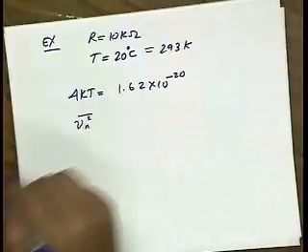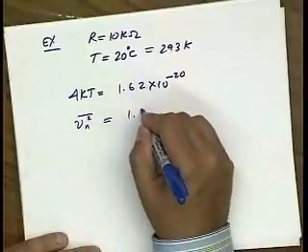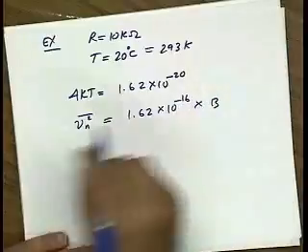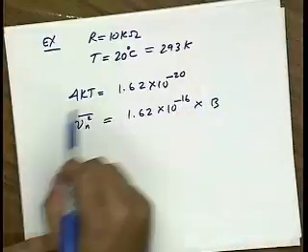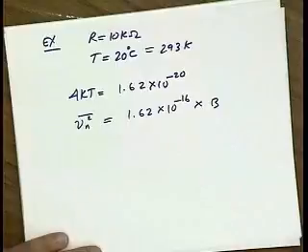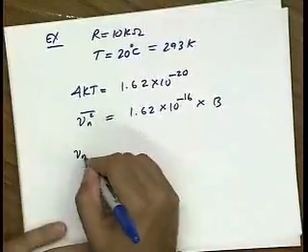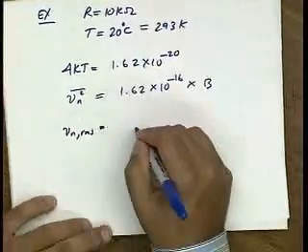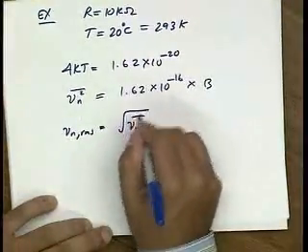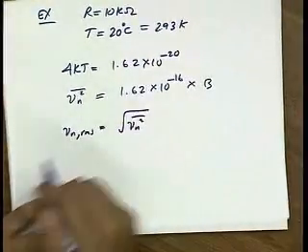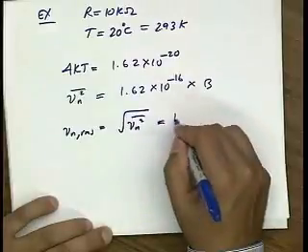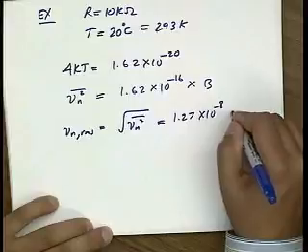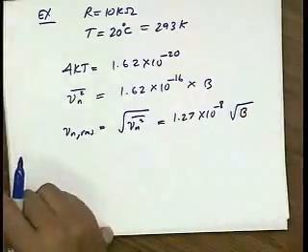So if I plug that in, Vn squared is going to be 1.62 times 10 to the minus 16 times the bandwidth. All right, that's just R times 4 kT. And so the RMS voltage is just square root, the root of the mean squared, and that gives us 1.27 times 10 to the minus 8 square root of bandwidth.